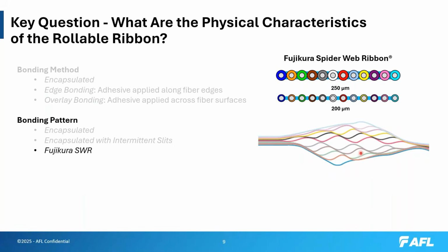As it bonds, it moves down, moves down, moves down. This lends itself to the fusion splicer, the fiber holders, making an almost as good as rigid ribbon splice. On a scale of 1 to 10, this is probably in the 8, 9 range. I find it to be fairly easy to work with, but it's not nearly as easy as the rigid ribbon that you're used to in the legacy fibers.